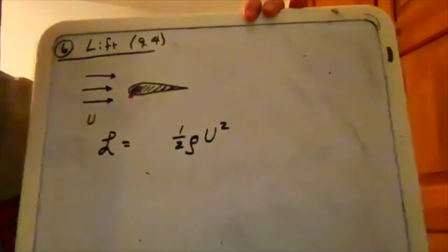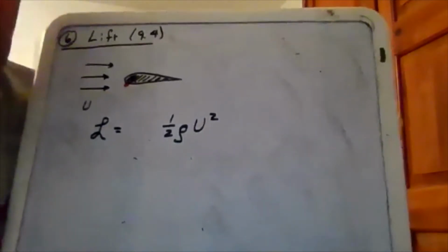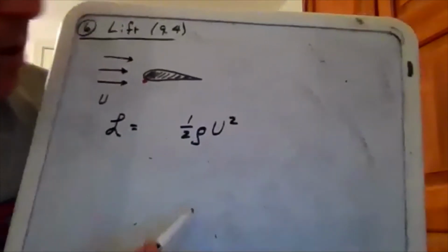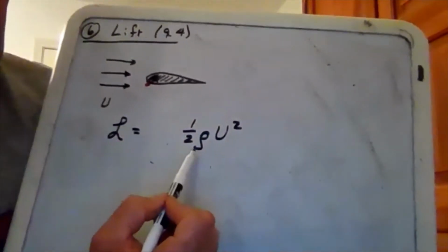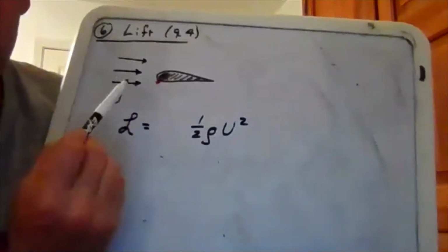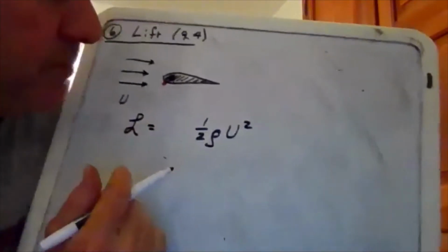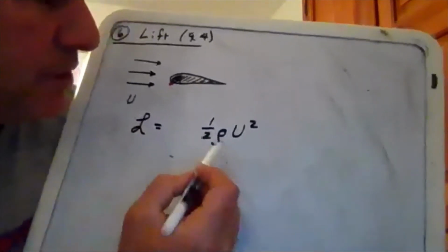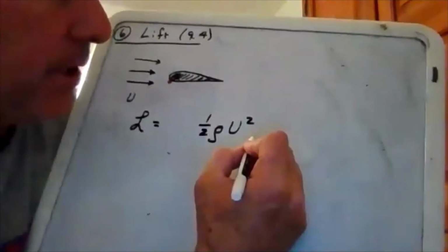All right, besides this conceptual stuff, I said it came down to one equation, and you guys can probably finish off that equation. It's very similar to the drag. So how are we going to get a lift on an object? Well, fluid dynamicists love to use this 1/2 rho u squared. It's the dynamic pressure. It basically characterizes the energy of this flowing unit in units like psi or newtons per meter squared. Okay, so let's say that's psi and we want to get a lift in pounds, we need to multiply it by an area.